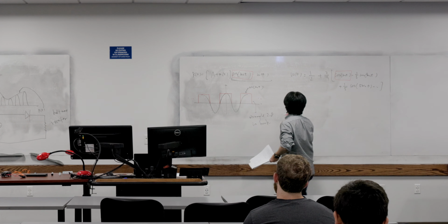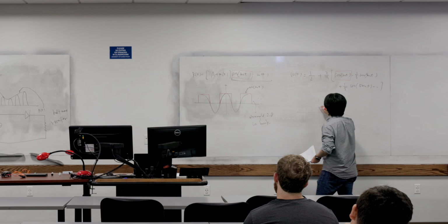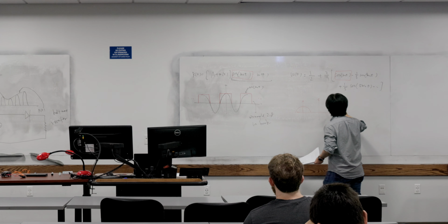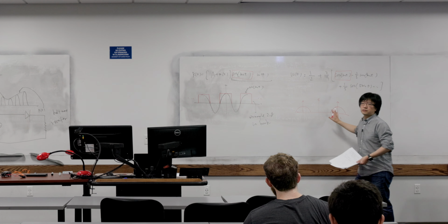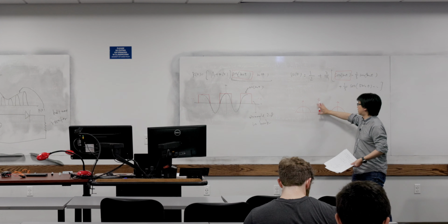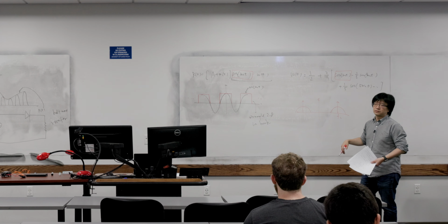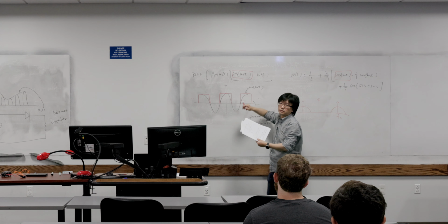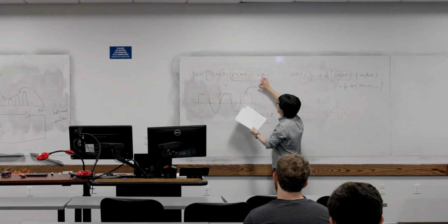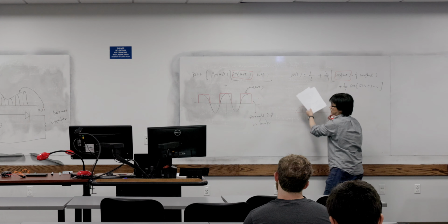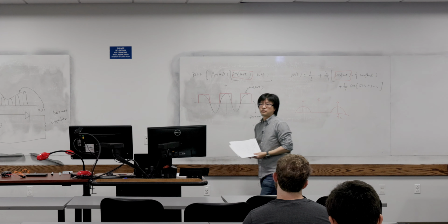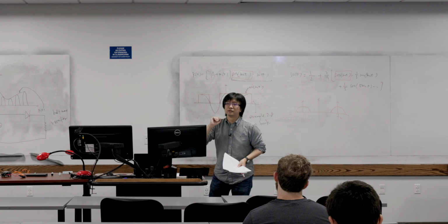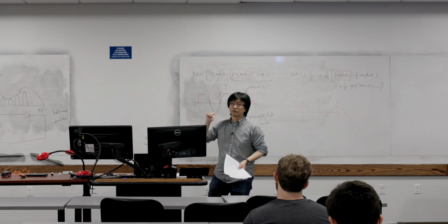If you remember, this is the modulated signal at fc. If we use a low-pass filter, then nothing will be left. This term is already high frequency. Therefore, if we multiply it by the constant, that part will be gone. Okay, I misunderstood what you said originally. Is that clear now? Great.